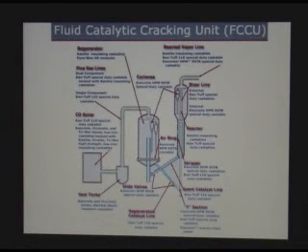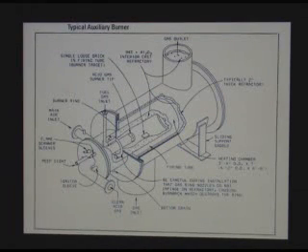This is a unit that uses extensively refractories almost everywhere, all kinds of refractories. It has a reducing atmosphere in this piece of equipment. Here is a riser which sees severe erosion, so do the cyclones here. So everything you see here is refractory lined basically. This is another piece of equipment where you have a lining inside a lining.